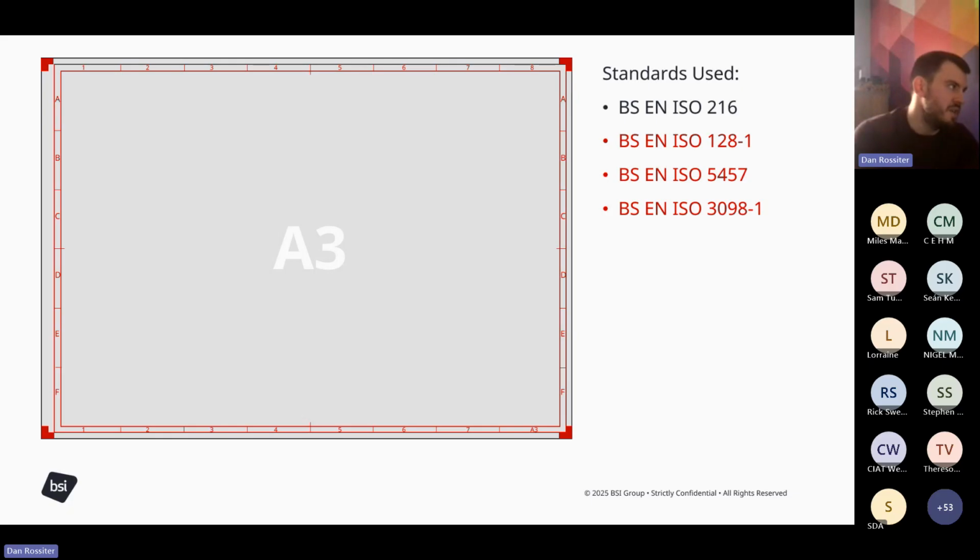You can now see the lettering inside the drawing border, so we can do that kind of quadrant aspect. So if I asked you to look for something in F7, you'd know it's down the bottom towards the right hand side, to aid with communication with someone. And you can see halfway across each one, you've got that slightly longer line, which is the centering marks, to help with trying to align stuff, whether it's been in storage, it's been saved on microfiche, or scanned in, to start to align and set things back up together.